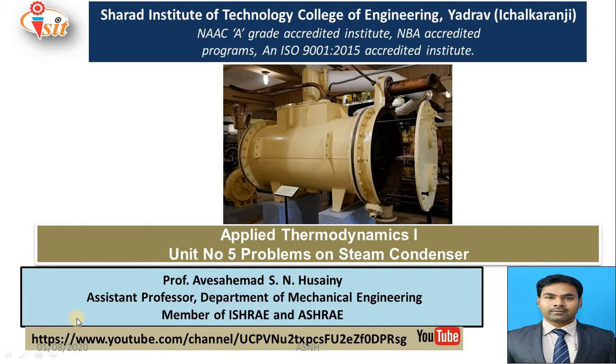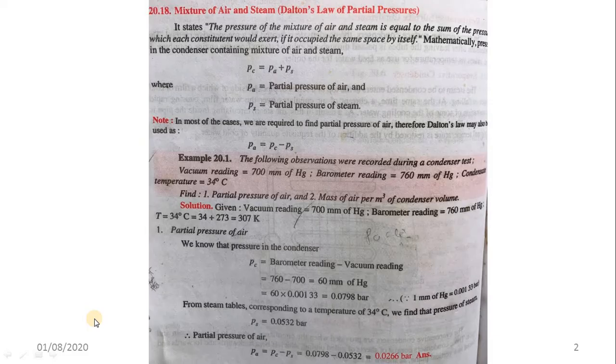So main specialty of condenser in case of the steam power plant is to improve the performance of that overall steam power plant. And the main function of that steam condenser is to keep the pressure lower after expansion process in the turbine, also to convert that steam to water and supply that condensate, that is water, again to the boiler through the different feed pumps with the help of that hot well arrangement. So here we will discuss some basic fundamentals about that steam condenser before starting the numericals.